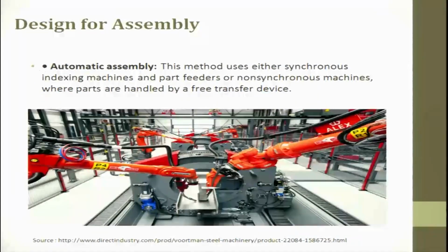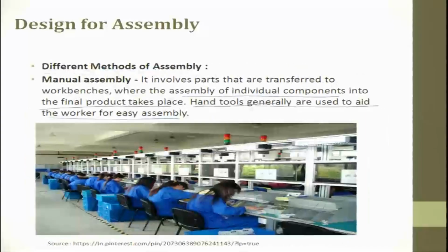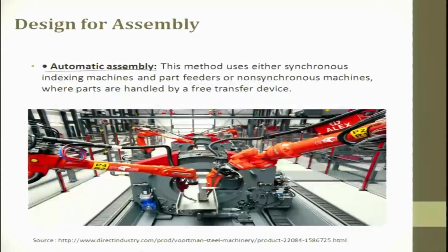The other way around, I do not want to have man. Why do I not want to have man? One, there is a possibility that defects can happen because of fatigue, and second, sometimes because of wrong judgment they could have done an assembly wrongly. And the forces they apply in fixing can vary from human to human. So, these are some of the possibilities for error when you do assembly in the manual way. In order to avoid this, we try to use automatic assembly.